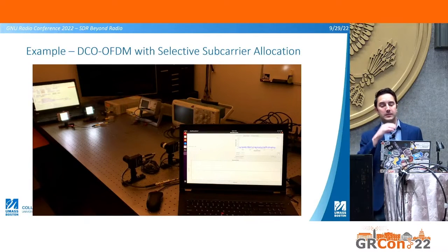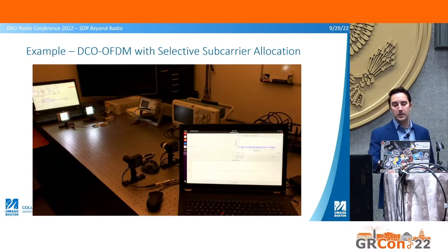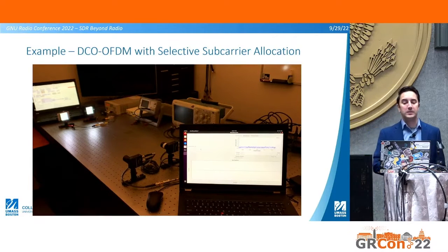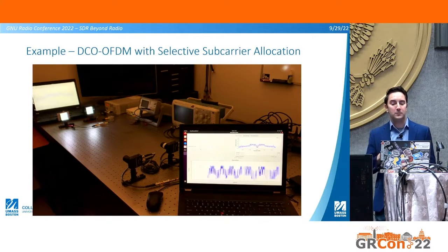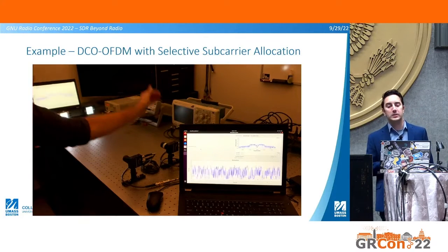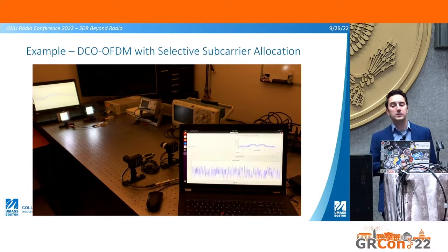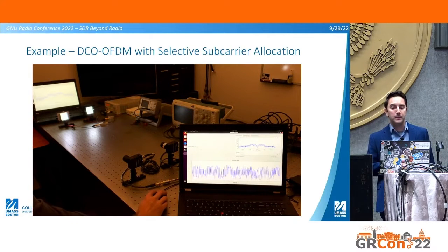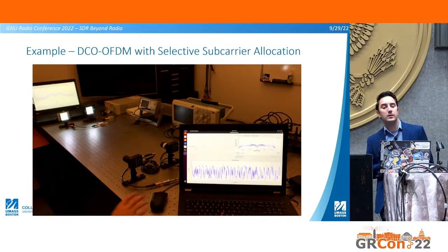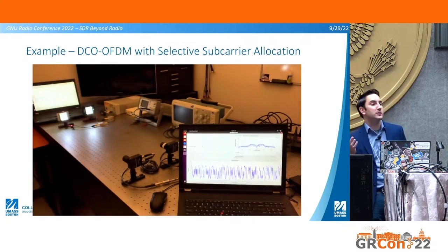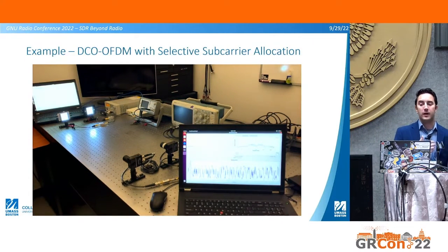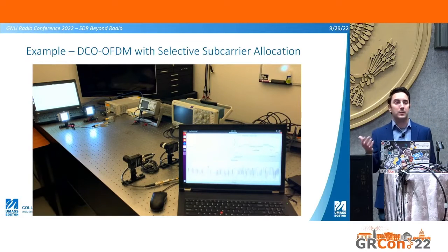This video now takes that DC OFDM waveform and ties it back to some of those characteristics, like the light interference we looked at before. Basically, we're doing a manually selectable subcarrier assignment in the system. So, a regular OFDM signal chain with that Hermitian symmetry in the middle, starting off with the low frequency subcarriers. And as that gets blocked, we lose the data. But if we change our receiver over to looking at the higher frequencies, it stops receiving anything until we go back to our transmit side and adjust to start sending on the higher frequency subcarriers. And we start picking up data again.